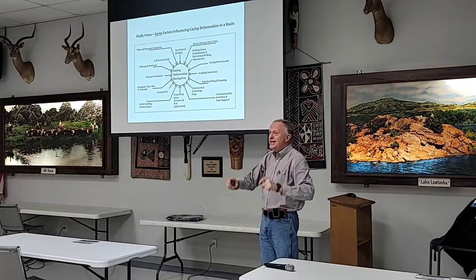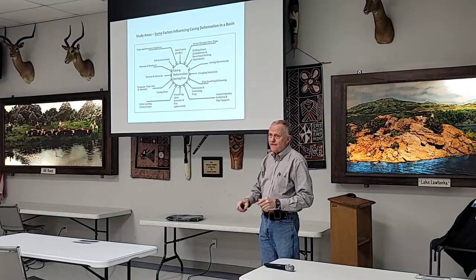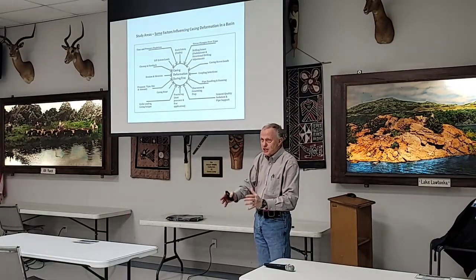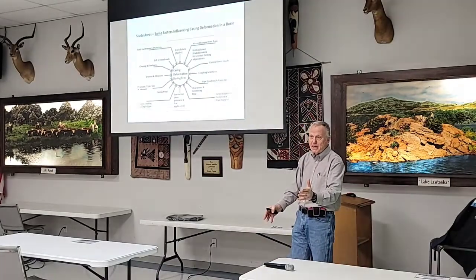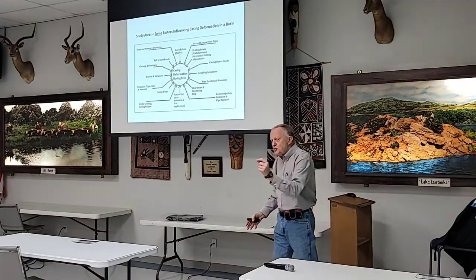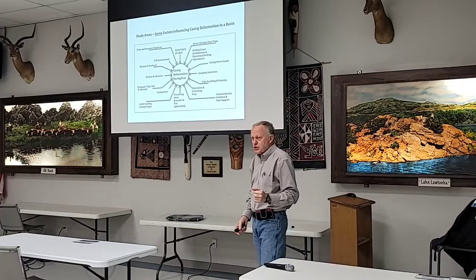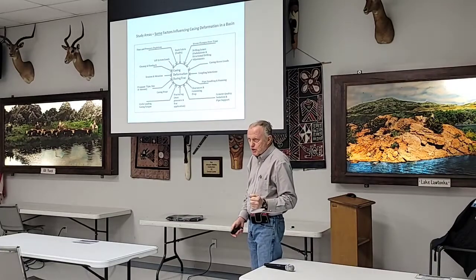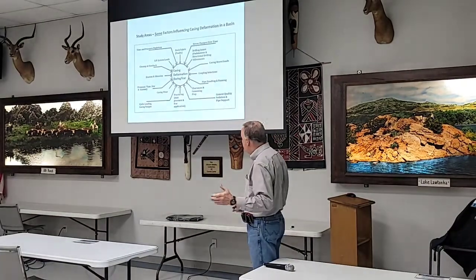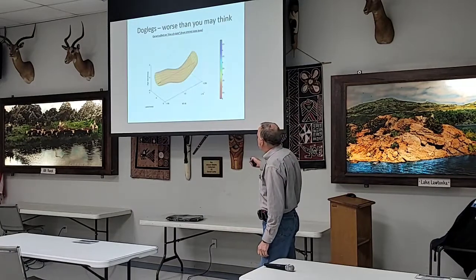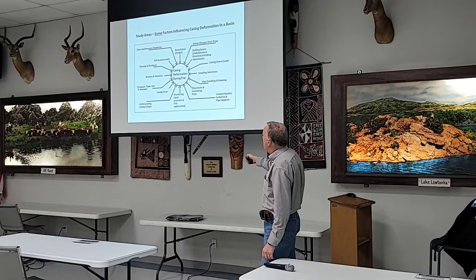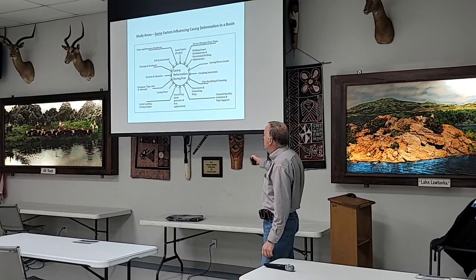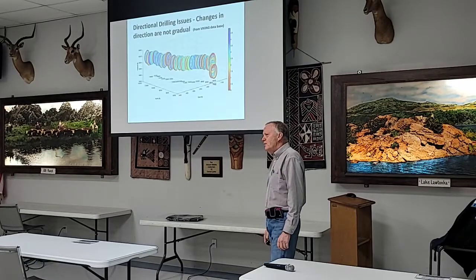erosion when that sand starts going down through there, because you have to get those boundary planes established, and that's usually about 15, 20 joints down the pipe. Use some premium couplings, especially in that upper section, or put some gap rings in there. That helps. And then you go around to some of the other clearances here, the proppant type, all of those things factor in, but this is what we look at when we tear down one of these problems.